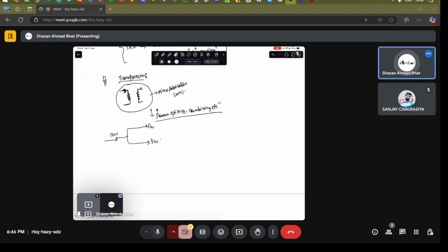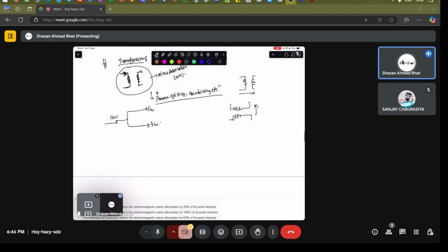If you fabricate a transformer in this direction, in the same plane, then it's called lateral coupling. If you have a transformer in the vertical plane, which is almost like a height, then it's called vertical coupling. And you know that the voltage of a transformer is L di1/dt minus M di2/dt. This is I1, this is I2. These are just simpler current-voltage equations that you have talked about.